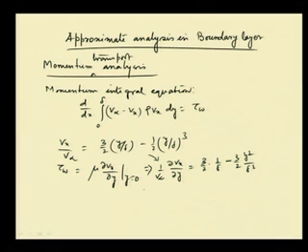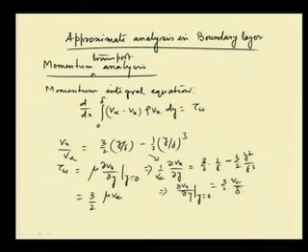From there, del Vx by del y at y equals to 0 is equal to 3 by 2 V infinity by delta, and the other term is 0. Therefore, tau w becomes 3 by 2 mu into V infinity by delta. Now, if I call this equation 1, and substitute in equation 1,